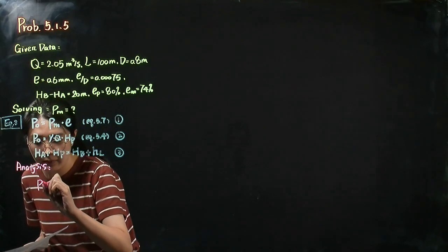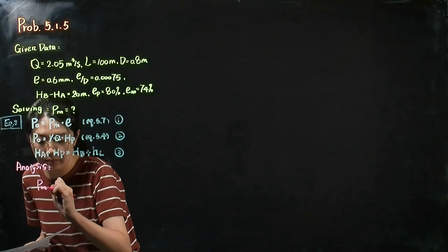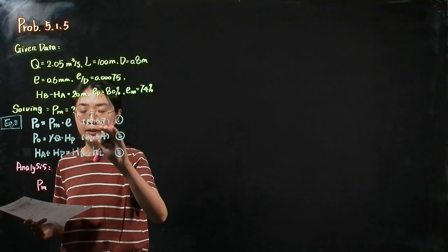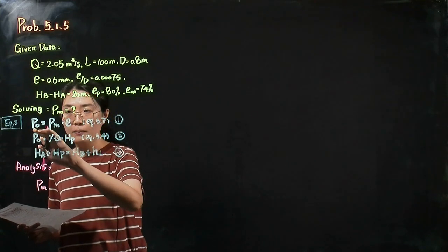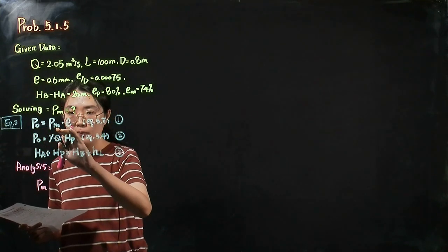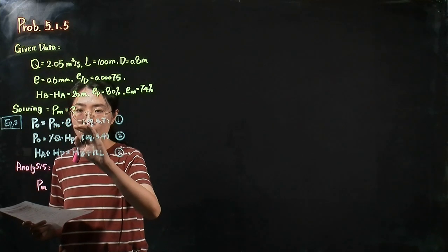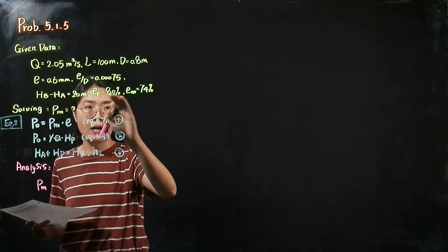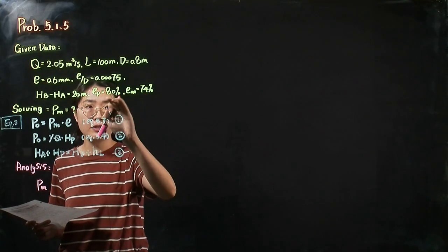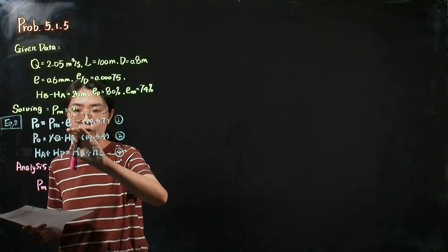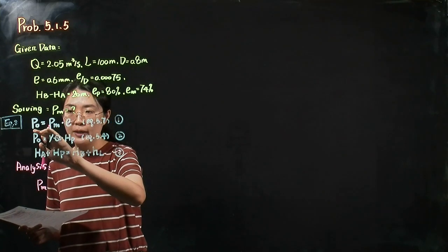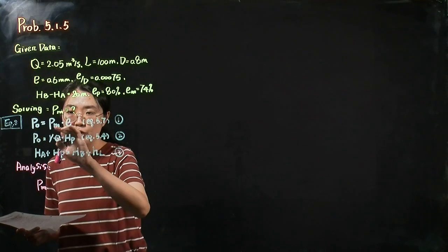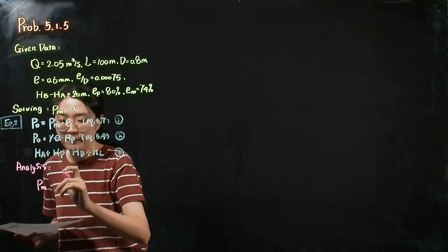We can find this parameter in equation 1. In equation 1, the output power equals the power requirement for the motor times the total efficiency. Because we already know the efficiency of the pump and the motor, if we multiply these two values together, we can get the total efficiency. So we need to calculate the output power, then calculate P sub m.